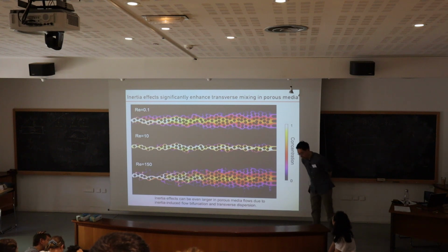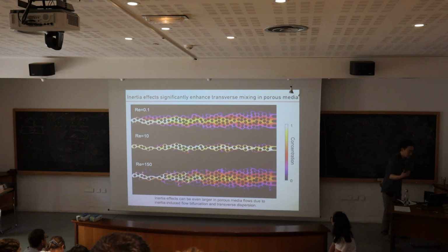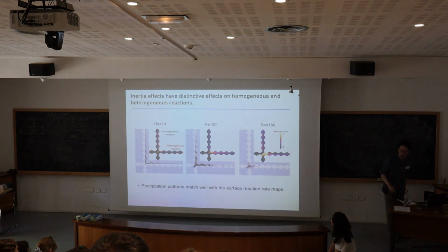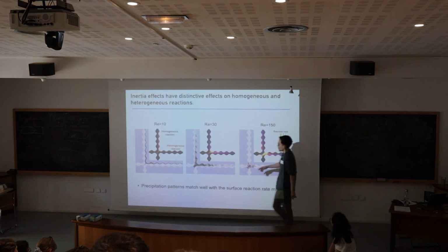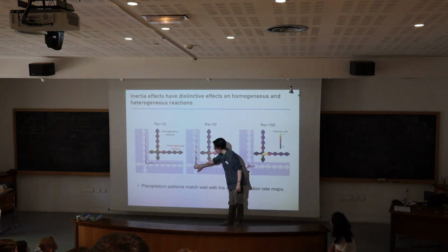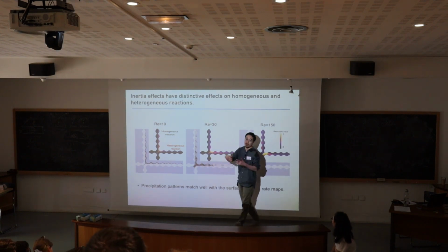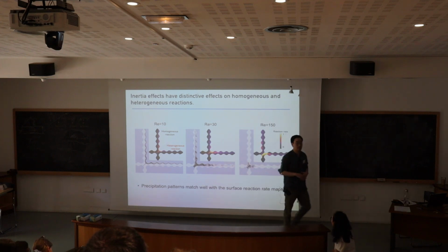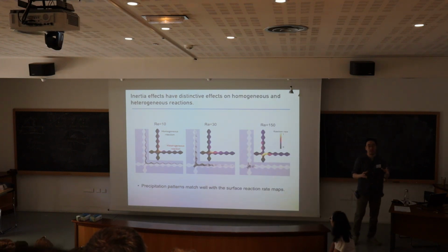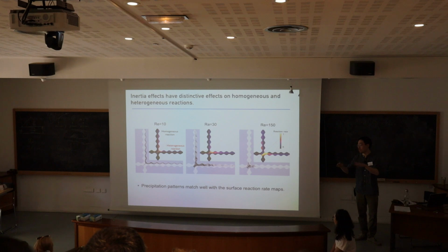Yeah, it really depends on the geometry, but in the end, I think we can explain everything with a streamline. That's what's nice about this. But here, small inertia can lead to a little bit of backflow, and that causes a lot of spreading downstream. So a really tiny effect of the structure can change the flow field, and that makes the difference in the impact.